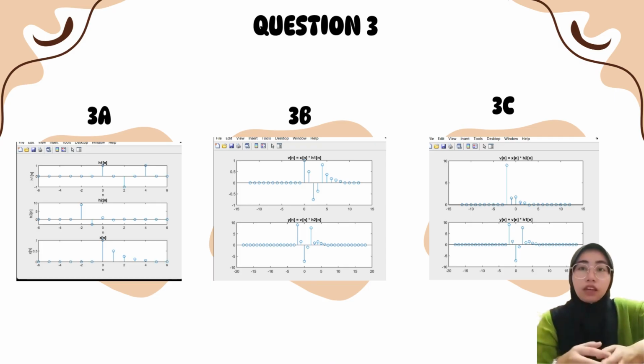Hi everyone, in this presentation, I walk you through question 3 on discrete time signals and systems, focusing on signal generation, plotting, and convolution method. For part A, we're given 3 discrete time signals, h1[n], h2[n], and x[n]. These are defined using delta and step functions, and we need to evaluate them over the range negative 6 to 6. Let's take a look at how we implement and plot them in MATLAB.